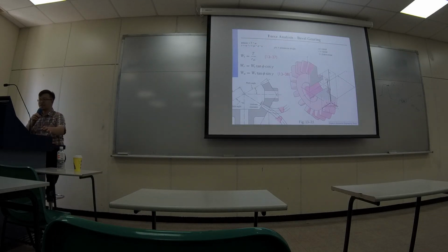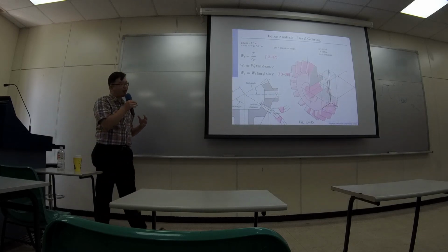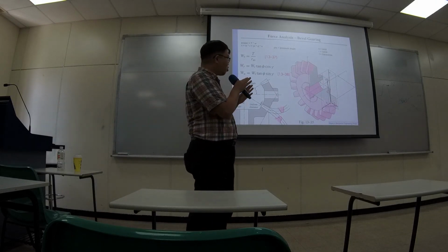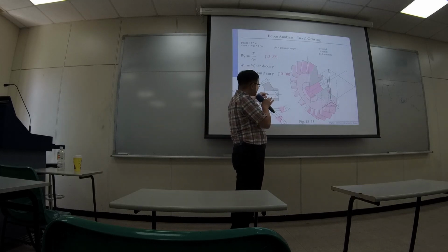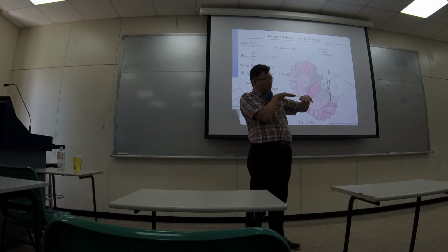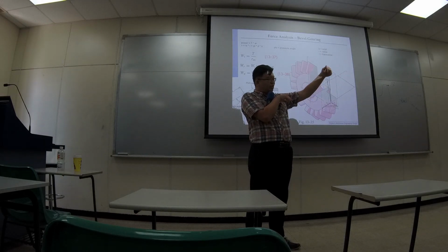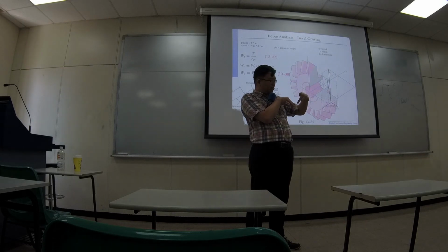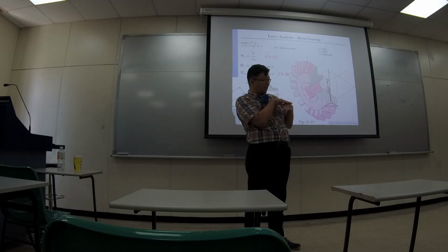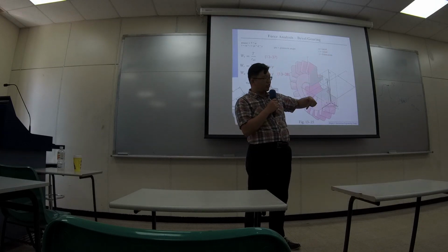So here's the complicated part. When we analyze bevel gears, the tooth profile stays on a cone shape, and since the profile is along a certain angle, the force coming from the opposite side of the teeth is going to apply perpendicularly to the tooth profile on my side, and that force vector is coming from a certain direction.